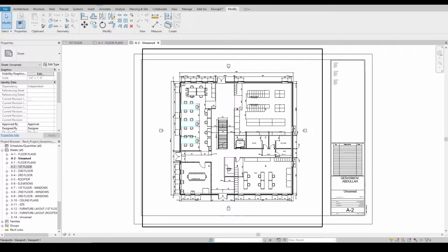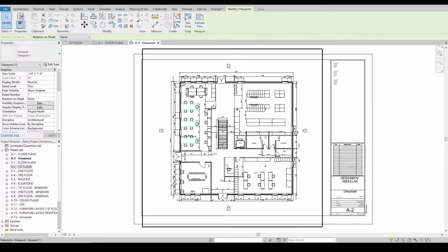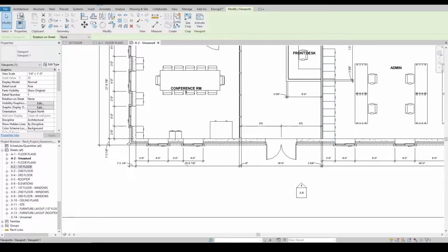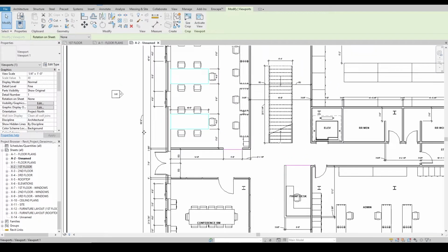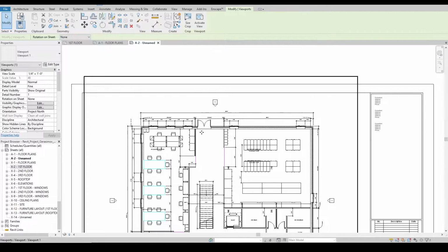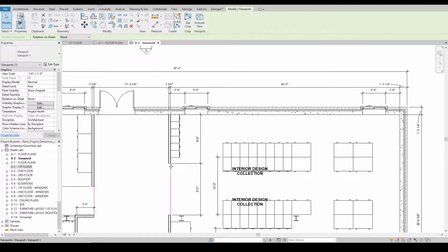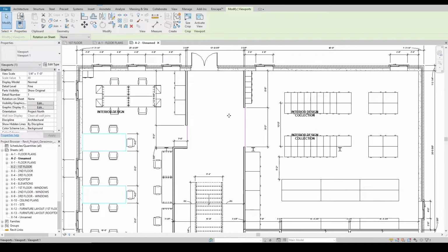This is my first floor plan enlarged with the dimensions labeled already. I want you to go ahead and only use your first floor plan in order to put these dimensions and put the room names into this floor plan. For instance, you can see I'm dimensioning exterior walls to interior walls. Since we have a square building, you don't have to dimension the squareness of the design for every side. You can see I have it 80 feet on one side, 80 feet on the other side. And then I dimensioned the location of interior walls, as well as half walls, as well as some furniture. So you will have a PDF of this available for your reference.